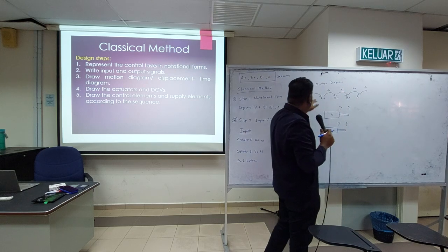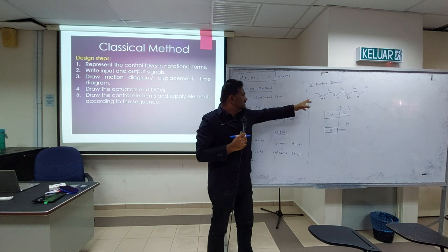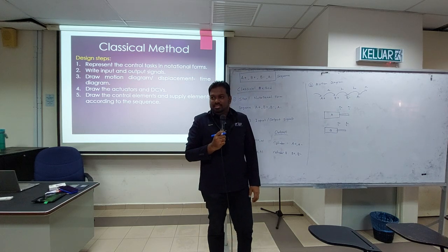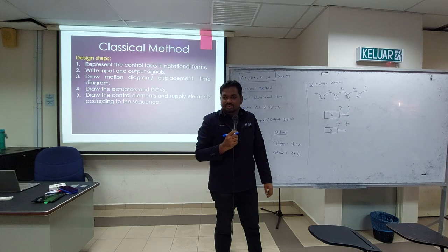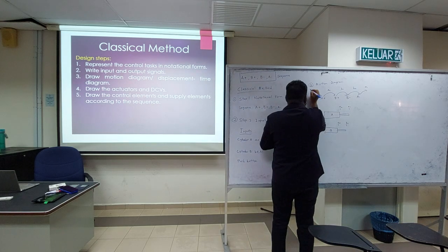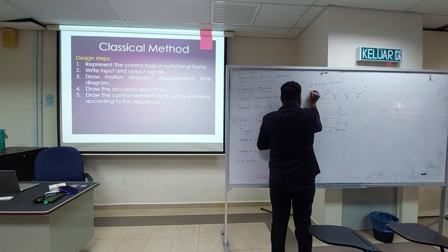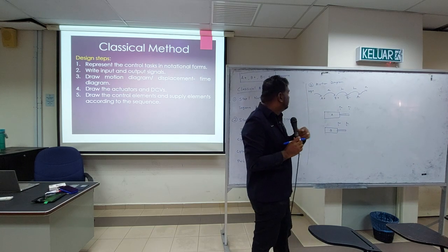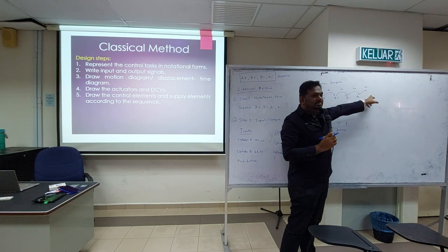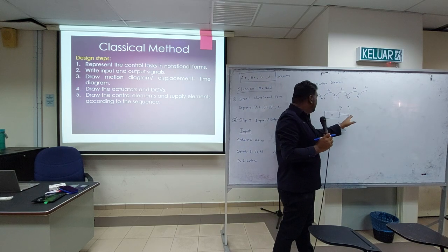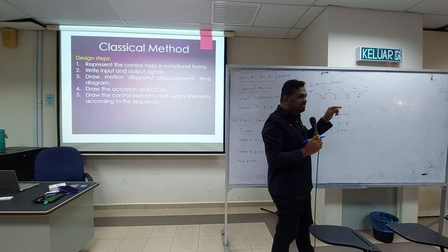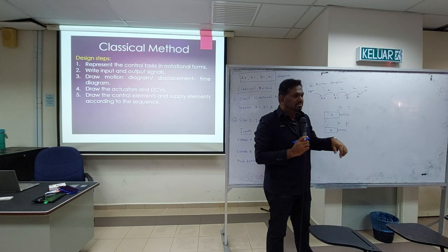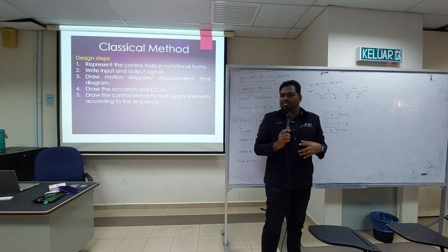Okay, here, what do we need? So how will you start the sequence? Yeah, push button. Okay, so start. So plus, it needs one condition. Take the last one, meaning cylinder A fully retracted, then you press the push button, only then the circuit will be on. Otherwise, there will be signal conflict.